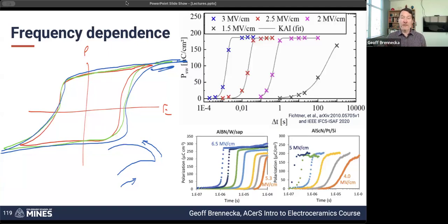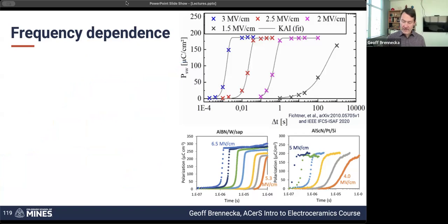So the charges that the circuit is measuring continue to increase, even though you're decreasing the field now. That is a really good indication that there's some loss mechanisms that are happening. If you get a nice sharp point up here that's fully saturated, that's a strong indication that you're not dominated by leakage. So that's the quick and easy, non-quantitative, but still very helpful approach.